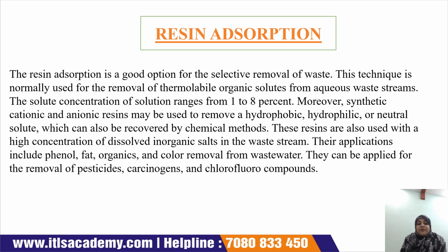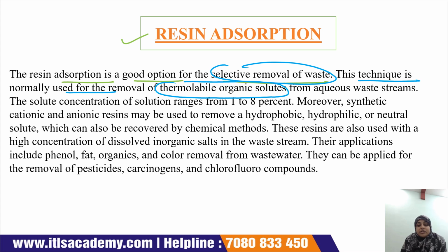Okay, so the first physical method is resin adsorption. Resin adsorption is a good option for selective removal of waste, and this technique is normally used for the removal of thermolabile organic solute from an aqueous waste stream. If we have an aqueous waste stream, then we use resin adsorption so that it will remove the thermolabile organic solute.